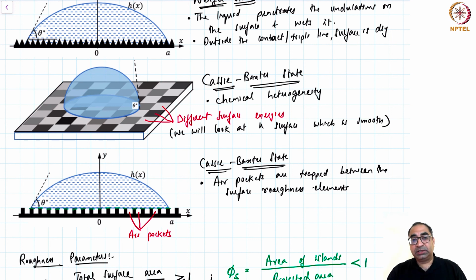One way you can promote a different kind of wetting is, let's say you take a Cassie-Baxter state with tiny air pockets, you could continuously shake the droplet and you could effectively change the wetting nature. We'll look at the Cassie-Baxter model where we have tiny air pockets between the roughness elements, and then we will look at some simple transition criteria, and it's not exhaustive by any means.